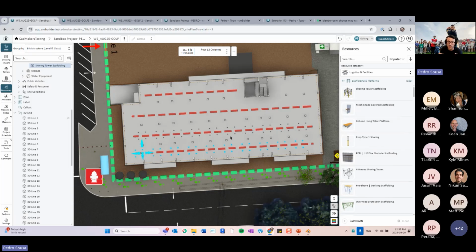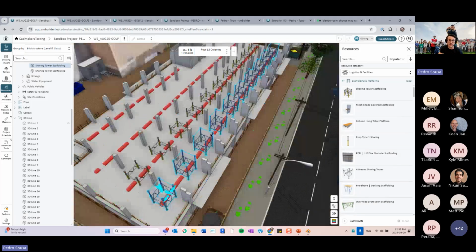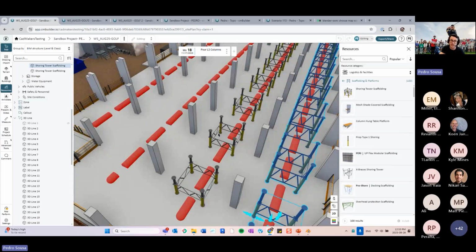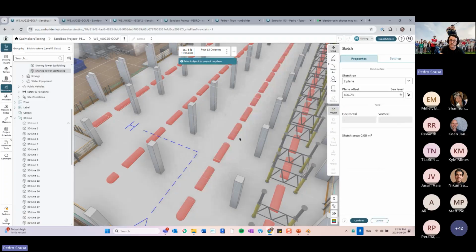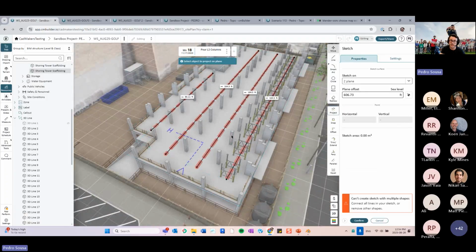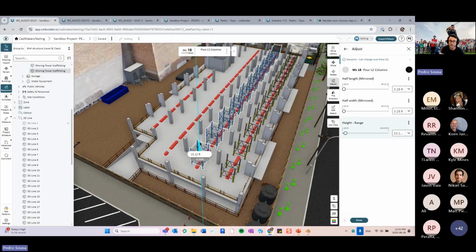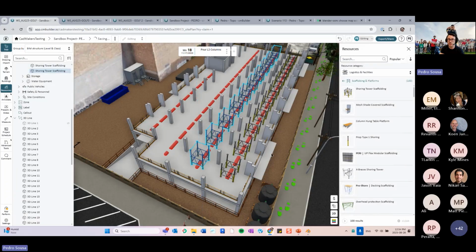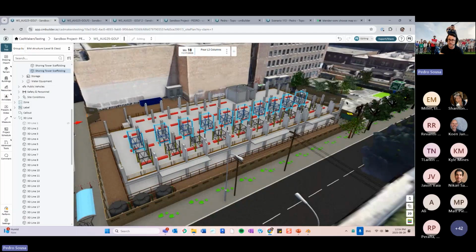But if I really want to place them on a defined spot, I will place this new object in here, and then I will go into the sketch, redraw, project the template of the lines, and then delete the ones that I don't want. Okay, so it's just a way for you to say, okay, I want the same object to be placed on the other side. Okay, so quick tips for you to create this. If you go onto the next, I won't do the rest, right? Just save some time here.